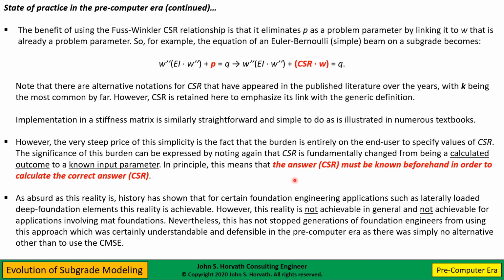But that's a very unique special situation where we've been able to do so many countless number of instrumented load tests on laterally loaded piles and drilled shafts and all sorts of deep foundations that we, in a sense, have gotten pretty good at knowing the answer beforehand so that we can calculate the correct answer on a project. But it is not true as a general statement. In general, for soil structure interaction problems, we cannot reasonably guess at the answer beforehand.